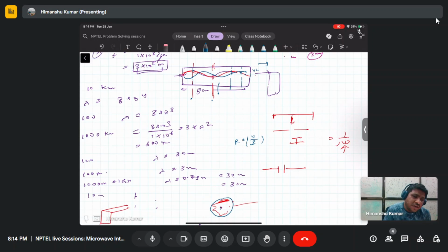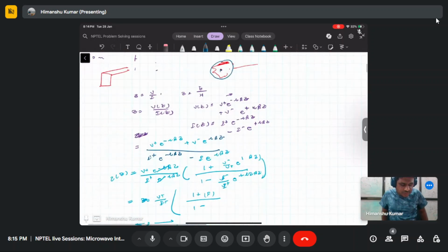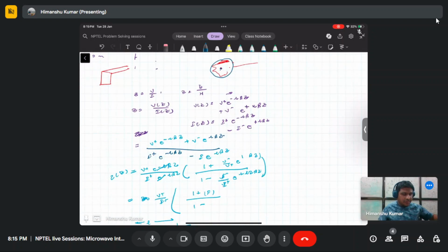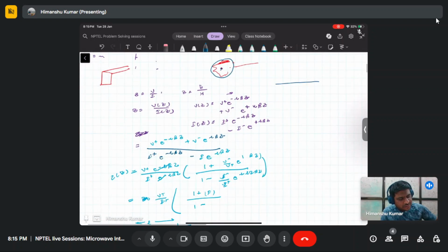You get my point? What I am trying to say. So the main modeling you need to consider is that there is a periodic variation of voltage and current wave along the transmission line, and you can't forgo that because your line length becomes comparable to the wavelength of the voltage and current. So along the line length you can't define a finite impedance.